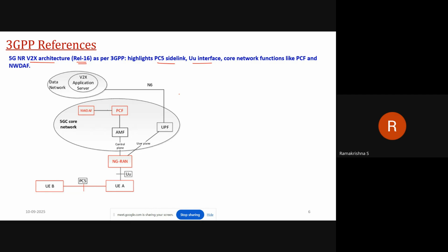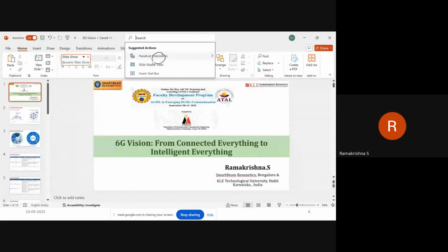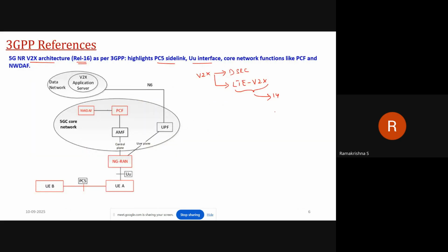So basically, when we talk about V2X, we had multiple options for V2X. One, we can say through other terrestrial networks, other than 4G, 5G, like DSRC. Other than that, we started with LTE over there. LTE V2X was one of the earlier specifications for V2X, which was specified in Release 14 and also some part in Release 15. This introduced the basics of side link, or the PC5 connection, as such, for vehicle communication. This is mostly broadcast messages for safety. Examples are BSM or CAM messages.